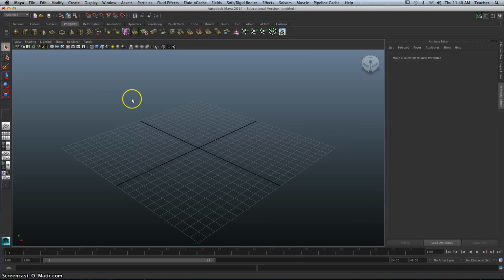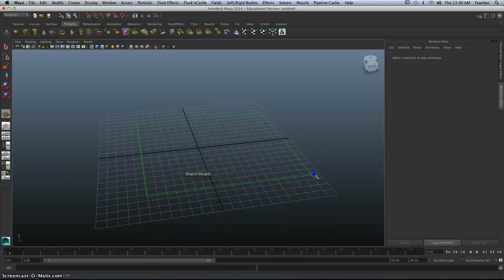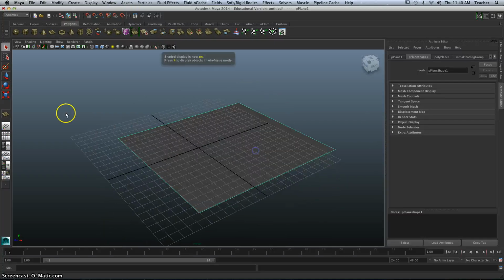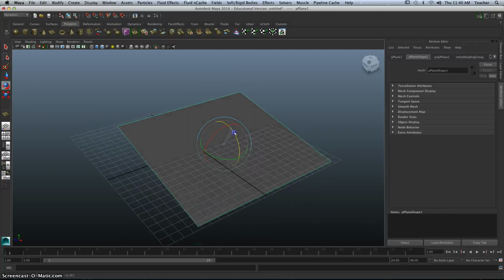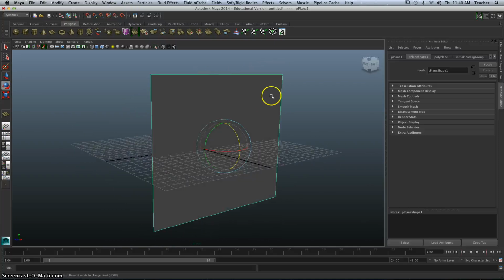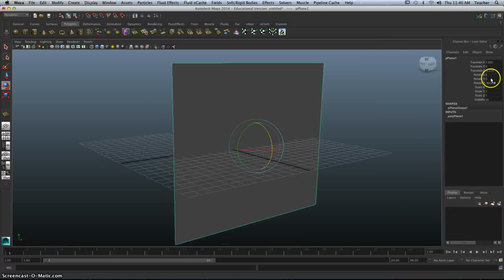Okay, so here we go. The first thing we need to do is start with a plane. So I'm going to drag out a nice plane here and press 5 to fill that in. I'm going to rotate this 90 degrees. It's facing us. Now, how do you know when you're exactly 90 degrees? Well, over here, I can click on this button right here, and we have a list of options, and you can see it's all of our coordinates. I got close. You can see my rotation on my z is negative 90.9. I'm just going to make it negative 90. Okay, great. And press enter.